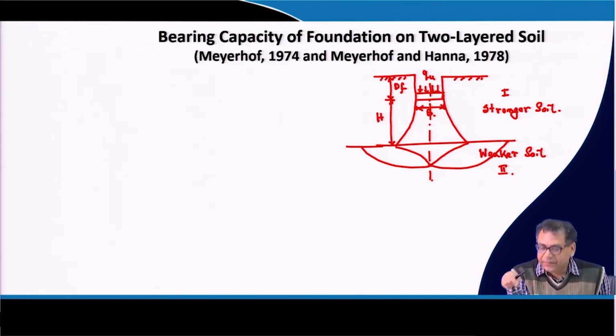As the stronger layer, the soil is basically going down, the foundation is going down and it is punching basically. So, there will be a punching type of shear failure in the stronger layer, because your weaker layer will fail, which is a very low strength layer. So, that means the total system will try to sink. Okay. So, that is why this type of failure surface is proposed.